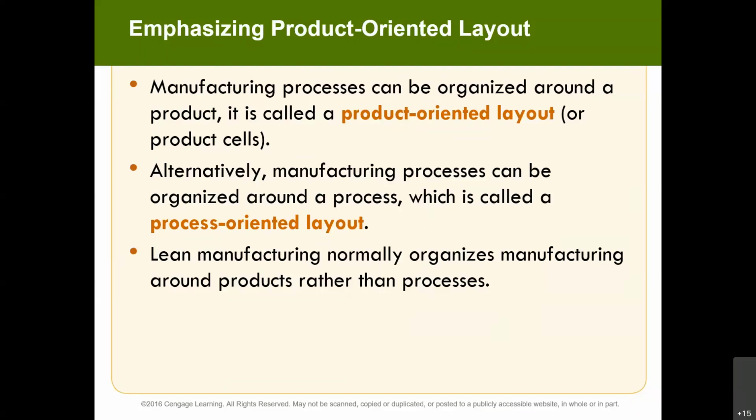The concept here is, if I organize my processes, my products in a logical way, I can reduce the amount of time it takes to go through the process. So think of it this way. If I have all of my raw materials at the very beginning stage, my yard, very close to the first entry point, meaning the machining stage, I'm reducing the amount of time it takes to get the raw materials to that machine, right? And so the shorter amount of time that takes, I'm reducing that amount of time. I'm becoming more lean in the manufacturing process.